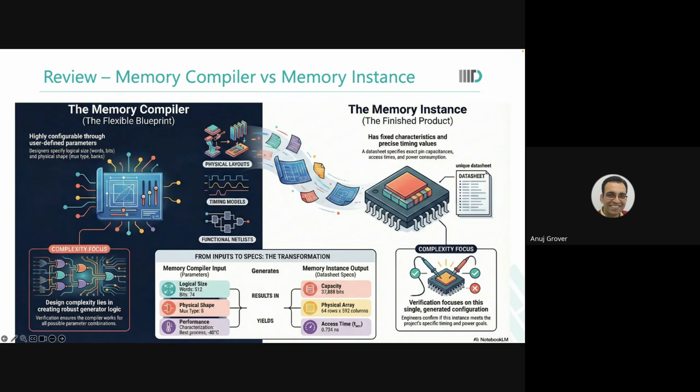But what do you know? Okay, this NAND gate, this is the size, X is this, Y is this, and the pins are at this location and that location. That was when the PNR tool could even place or route your cell. Are you with me? It did the entire PNR. Then at a much later stage, you brought in the layout so that you could now do DRC.